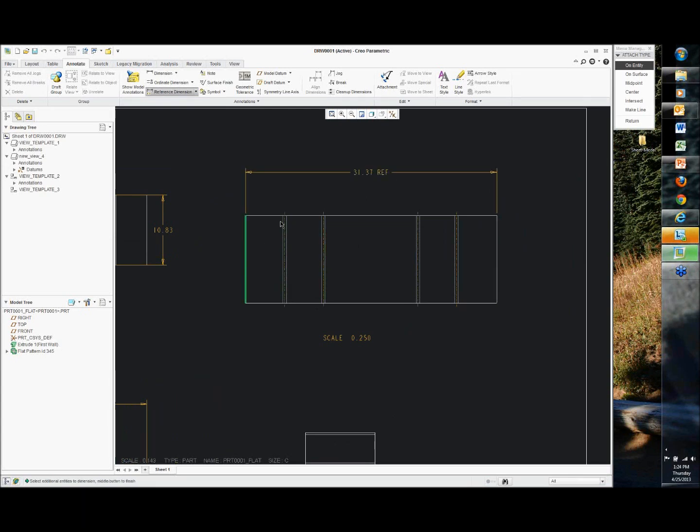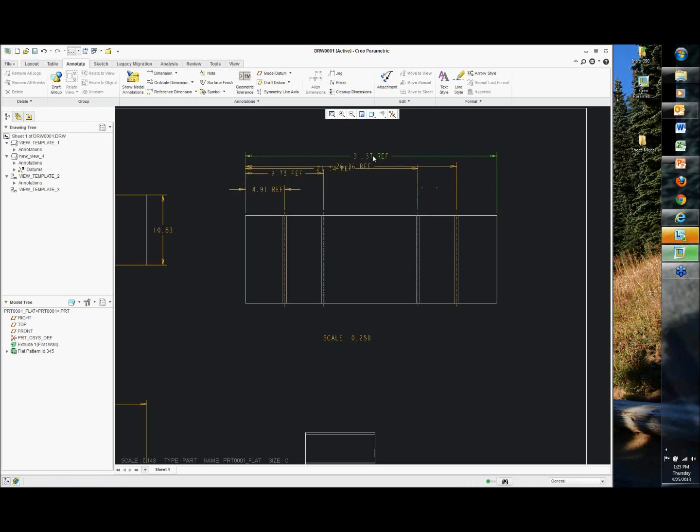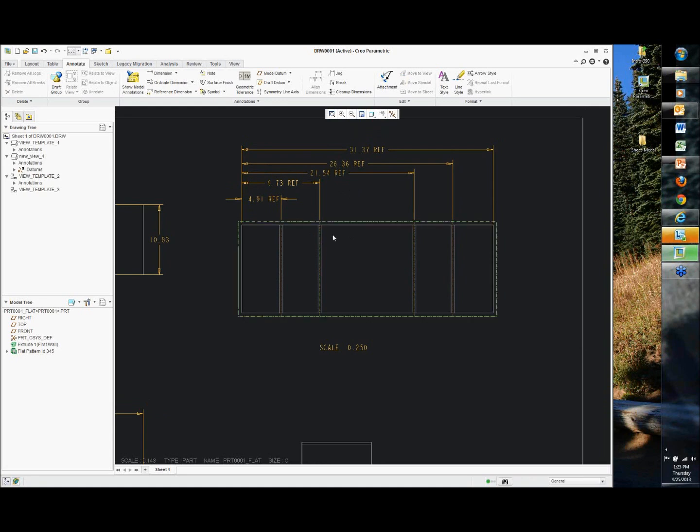And that brings up another question that we asked too, and that was how many people are using the default built-in reference and how many are building directly using a bend table, right? Because these dimensions that I got in here are coming from the PTC default. Not that PTC created the default bend deduction system, but it's just using a formula. It's not taking anything into consideration as far as the bends, the dies that each individual shop uses.